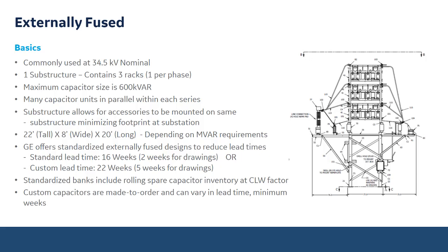We provide a catalog which will identify MVAR requirements at 34.5 kV, and there's a selection table, so we can select the MVAR requirements, which will include the cap switcher here, the arresters, ground switch, and a PT. This is pretty much a standard offering, and we've had pretty good success with this.